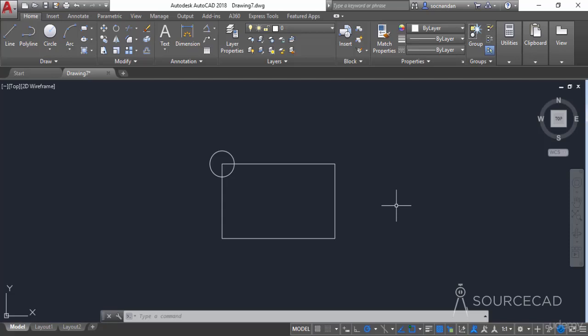In this video, I will tell you about move and copy tools of AutoCAD. So here we have this rectangle and we have a circle here on one of the vertices. Now let's say that we want to move this circle on the second vertex here. So for that, we can select the move tool from the modify panel.